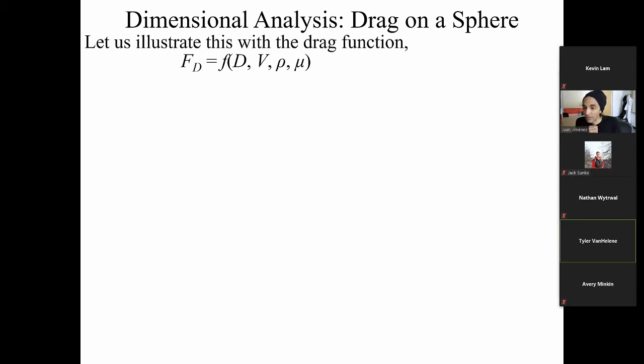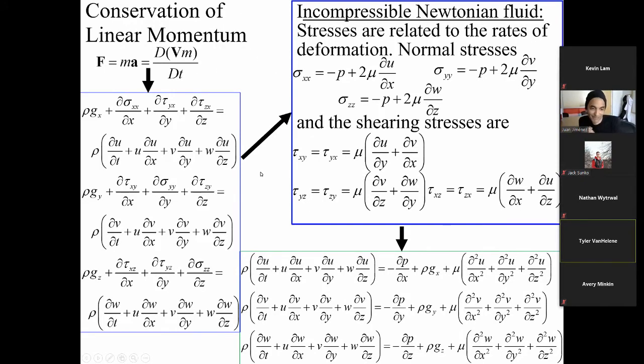Yeah. So on the previous slide, I had a question. The thing that I'm confused about is how will we use those equations in the top right in regards to all of these lines in the bottom? Yeah, so these on the top right are already in here. What happens is you take these equations, the linear momentum equation, and these come together, and then you end up with the Navier-Stokes equation down here. Okay, so in an actual problem, we would just be plugging in the numbers into the Navier-Stokes equation. We wouldn't have to derive them first.